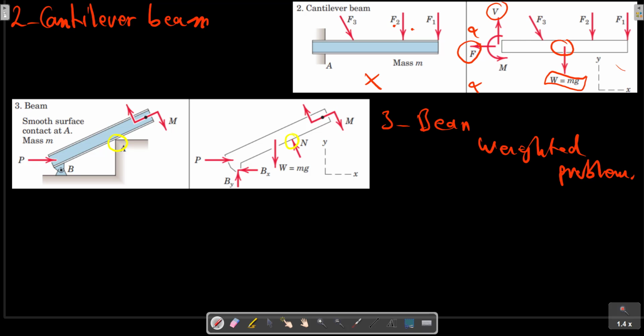The force exerted by the corner A on the beam is normal to the smooth surface of the beam. To perceive this action more clearly, visualize an enlargement of the contact point A, which would appear somewhat rounded, and consider the force exerted by this rounded corner on the straight surface of the beam, which is assumed to be smooth. If the contacting surface at the corner were not smooth, a tangential frictional component of force could exist.